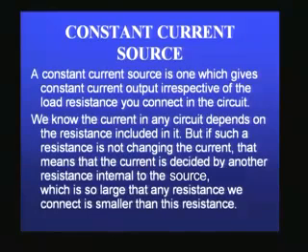The constant current source is basically different from the constant voltage source. If I have a simple circuit with a voltage battery or a voltage source and a resistance and all that, you already know that every voltage source is also associated with an internal resistance. Therefore, when I look at a voltage source, I should always remember there are two things in this. One is an ideal voltage source which has got zero internal resistance. Added to that is an internal resistance which is corresponding to the voltage source that we are looking at. Therefore, any given voltage source can be equivalently represented by two items. One is an ideal voltage source which has got zero internal resistance, as you all know, and a series resistance which is actually the internal resistance of the voltage source that we have.